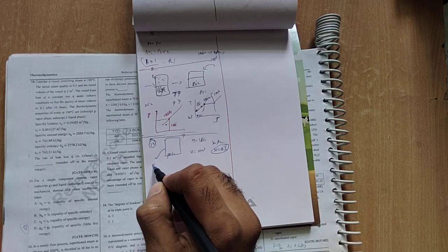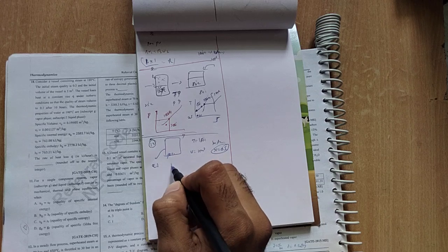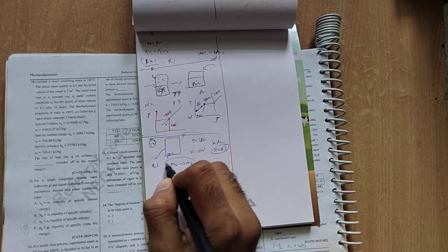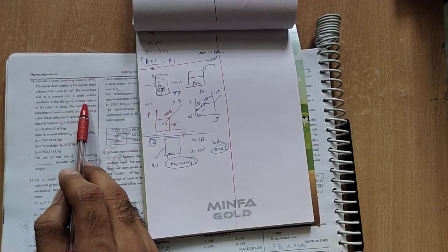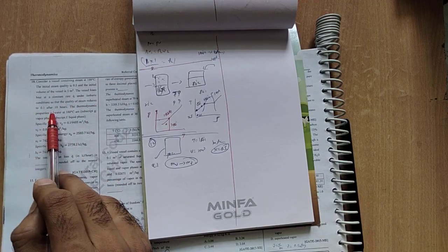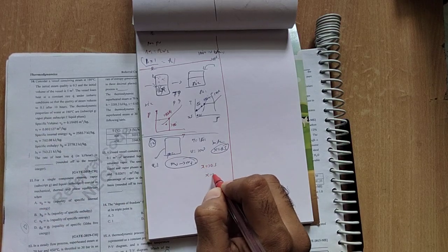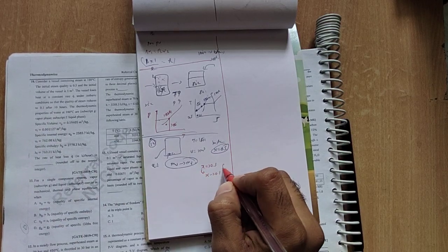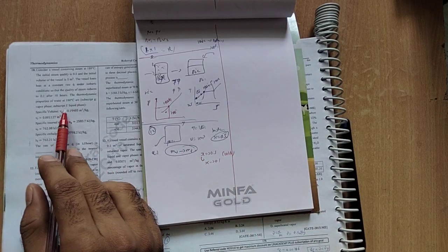So heat is lost, Q is lost. So definitely the mass of vapor will convert to mass of liquid. So you can see the quality of steam reduces to 0.1. So x is at the beginning 0.5, now it is reduced to 0.1, at a 10 hours duration, for 180 degrees Celsius.